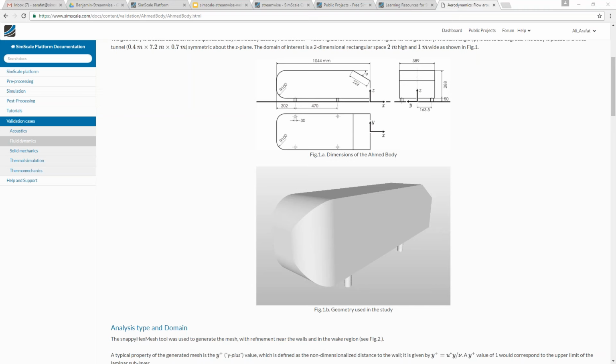But the flow in the wind tunnel is perfectly lined up with the wind tunnel axis only at the inlet, not in the separation zone in the vortex region, of course. This can be captured by the 5-hole probe, not in the fully separated backflow region as I mentioned before, but of course in the other regions.